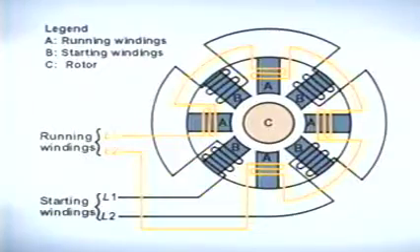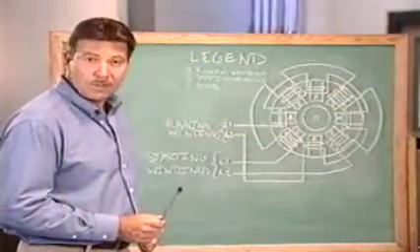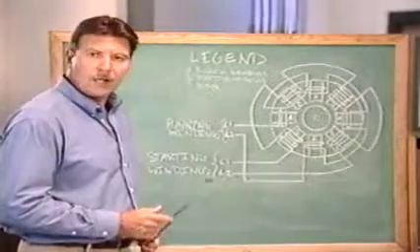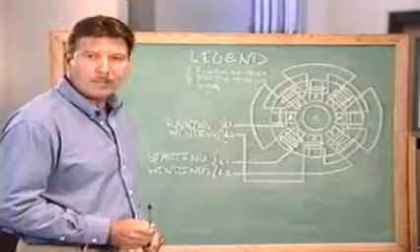to the motor. The start winding is a higher resistance coil that is only energized long enough to get the motor started. The start winding is removed from the active circuit by a device such as a centrifugal switch, which opens and closes its contacts based on the speed of the motor. The difference in the resistance between the two windings creates magnetic fields of different strengths, generating the needed starting torque